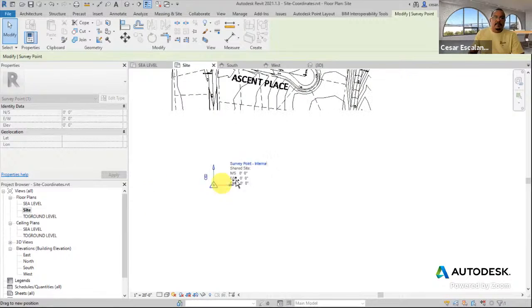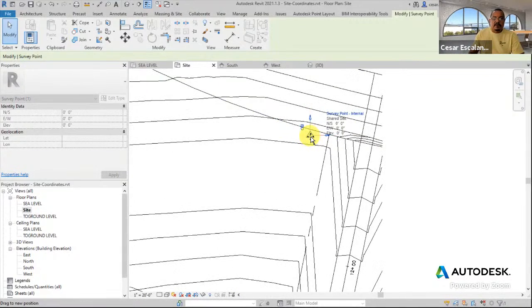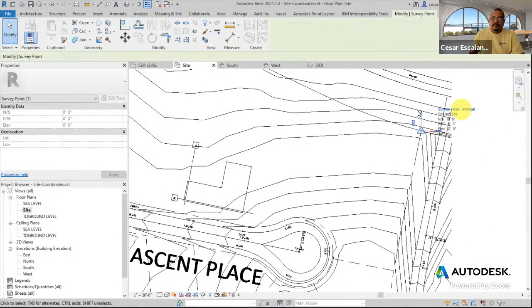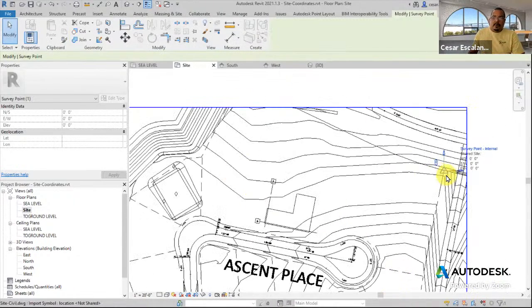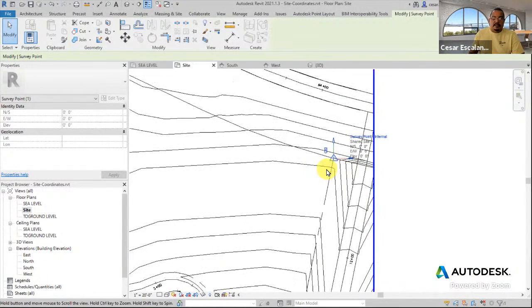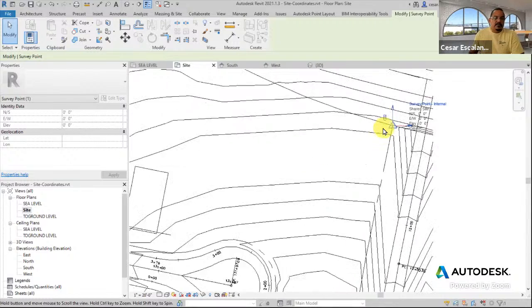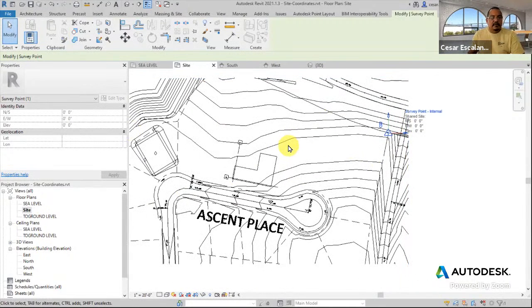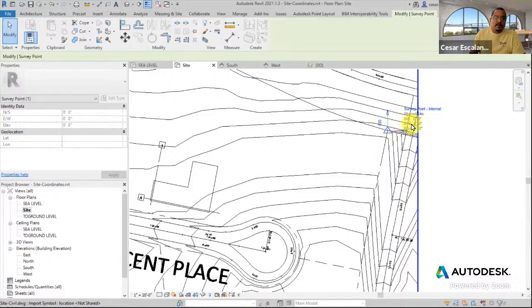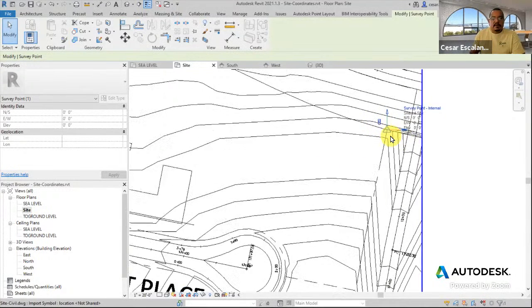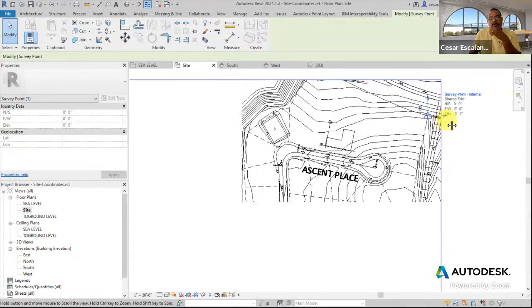I'm going to move the survey point all the way to the corner at the upper right side of the coordinate system of the perimeter. So this property line corner is what we identify to be the project survey point. You can pick another one. It really is a relative point, but it needs to be at the ground level. So the coordinate and elevation are always going to be 0. And then you have the north-south, east-west coordinates as 0, and I snap it to this point location.